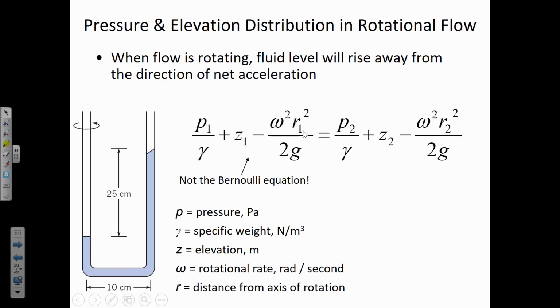Now it has to be the same fluid connecting the 2 points. Like if I had partly oil and partly water in here, I couldn't go from one point to the other. I have to go through one consistent fluid, and then I could solve a multi-fluid problem in steps, just like we did with the hydrostatic equation.